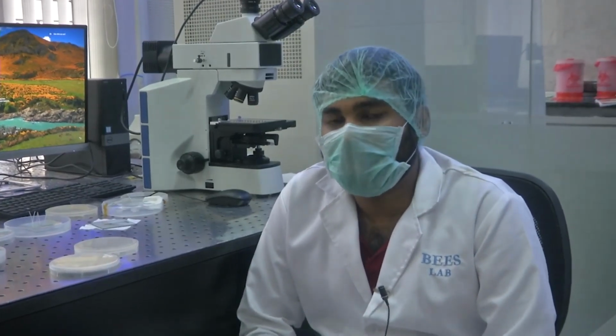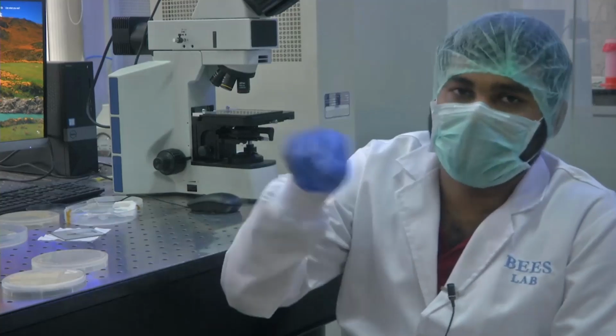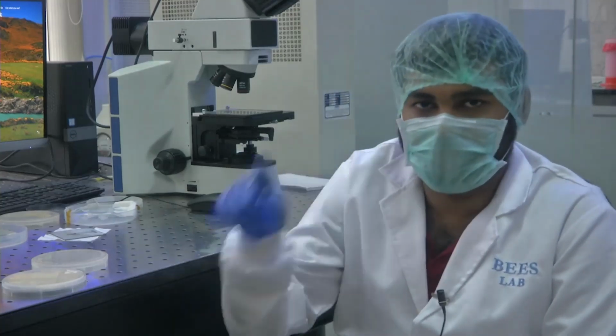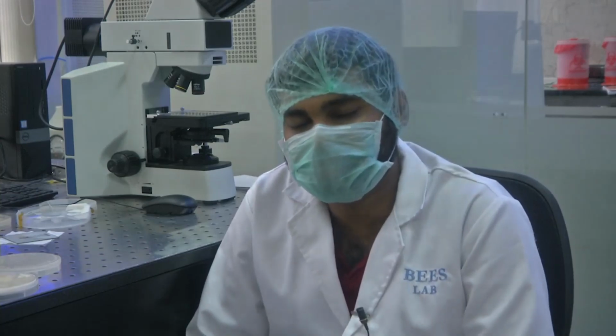How? Because of resistance. Let's say you are designing a micro heater. You make a micro heater like this, with a winding structure. I am just showing in my hand, making a winding structure. Now how do you design? Your design is that this much resistance should be there in the micro heater. When this much resistance is there and I apply a voltage, this much current will flow through that resistance and there will be I squared R losses. These I squared R losses will be dissipated as heat.